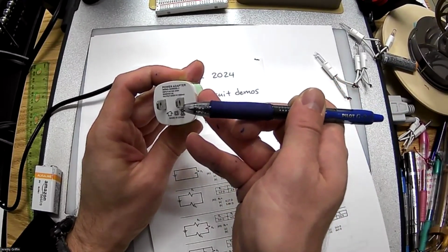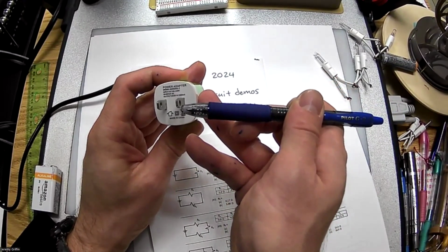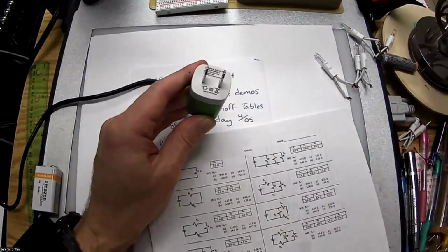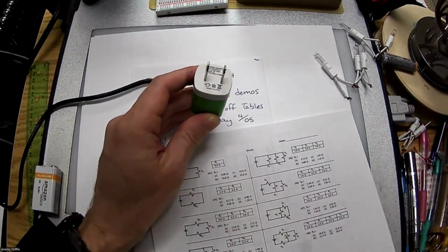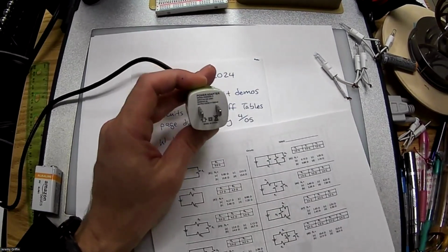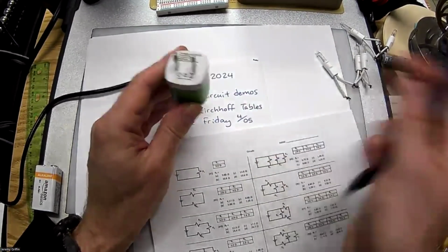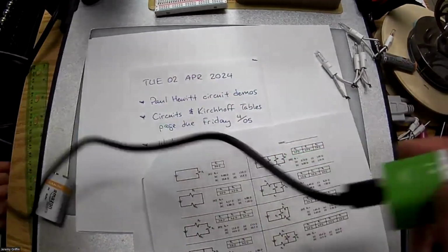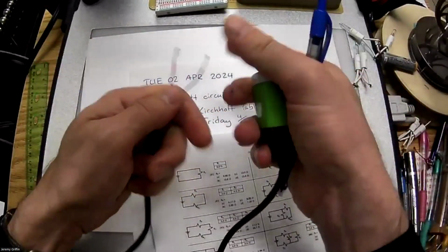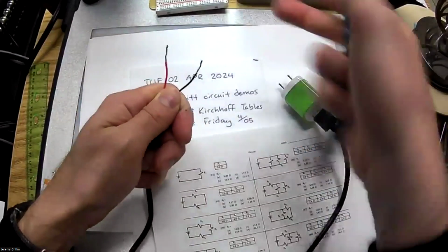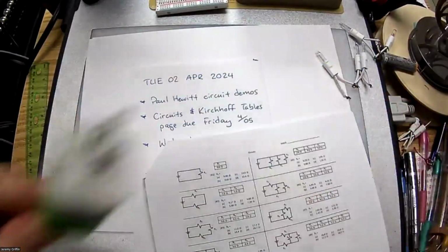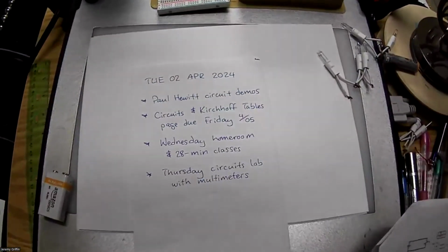Does it mention frequency? Sometimes they'll mention a frequency standard too, and they'll usually take either 50 or 60 hertz. This one doesn't mention it, but it will output 5 volts DC, which again I was talking about yesterday. It's safe: I can cut the leads on the other end, and even with this plugged in, it's not going to shock me. It's just going to be 5 volts.